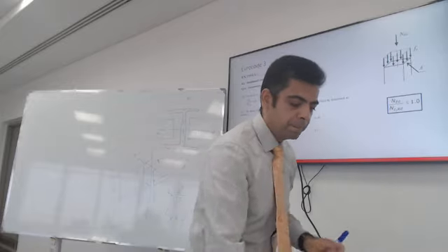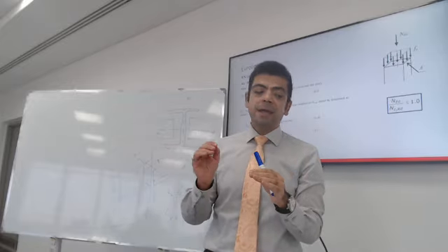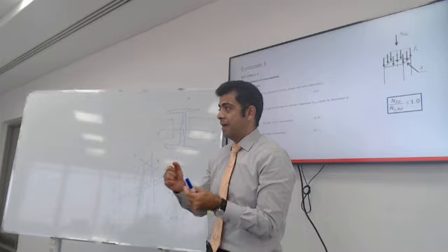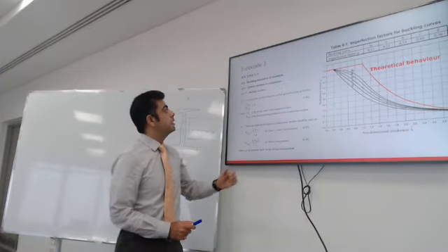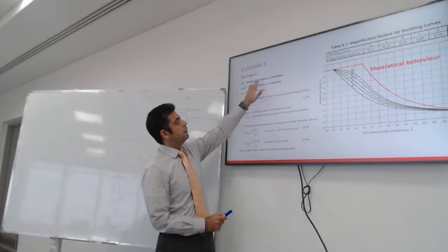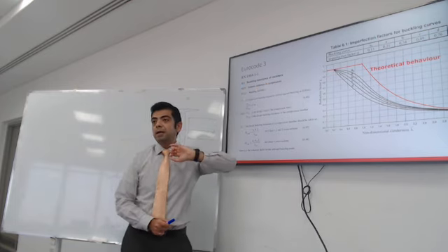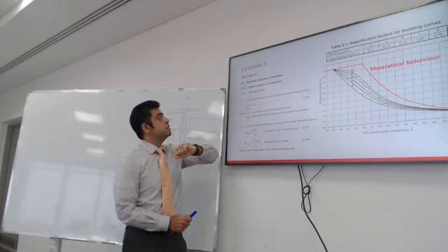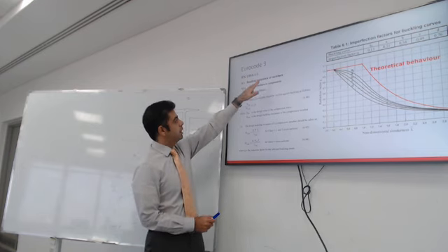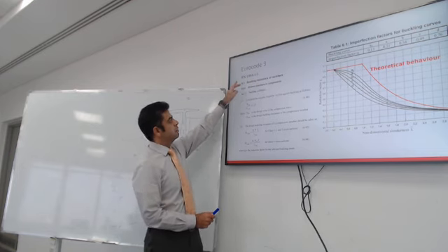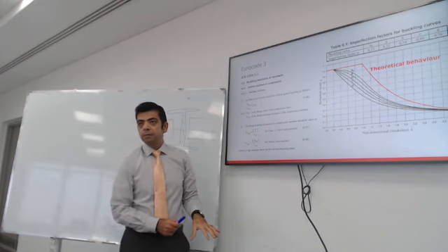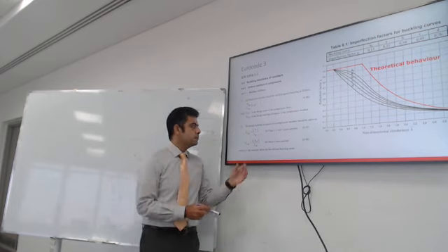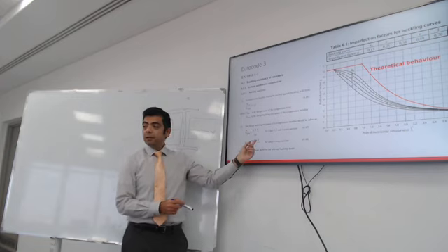So in this step, first check if the column is short and stiff. If the column is tall, you need to consider the buckling resistance for the column or the member. So this is the Eurocode 3, section 6.3. These are the exact equations of the code. It tells us to account for buckling.